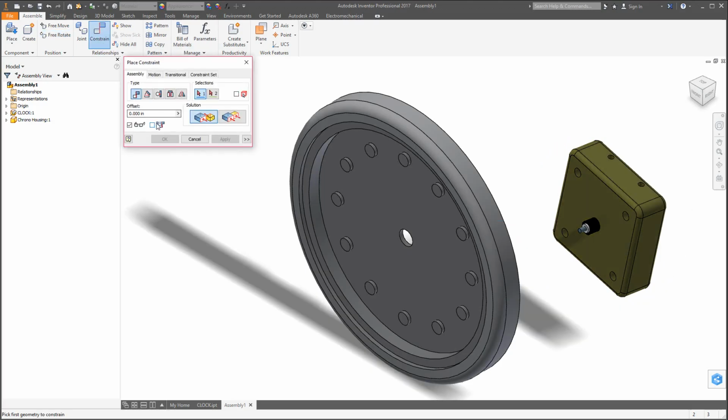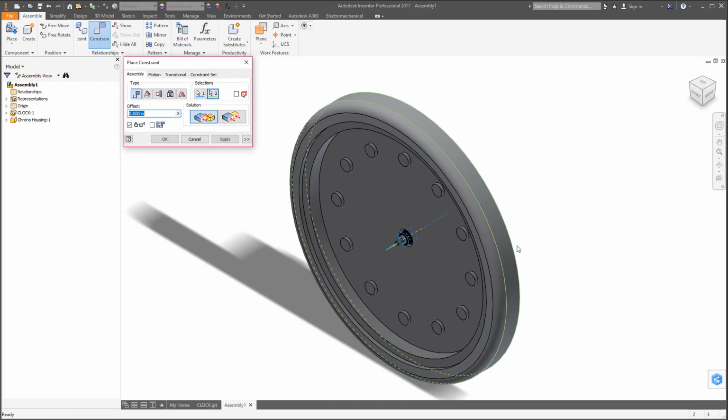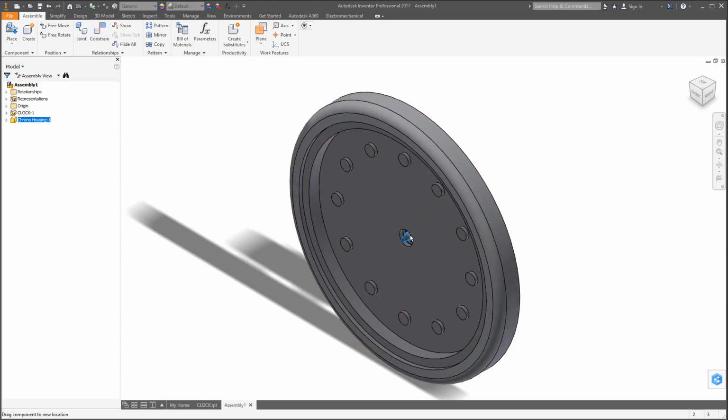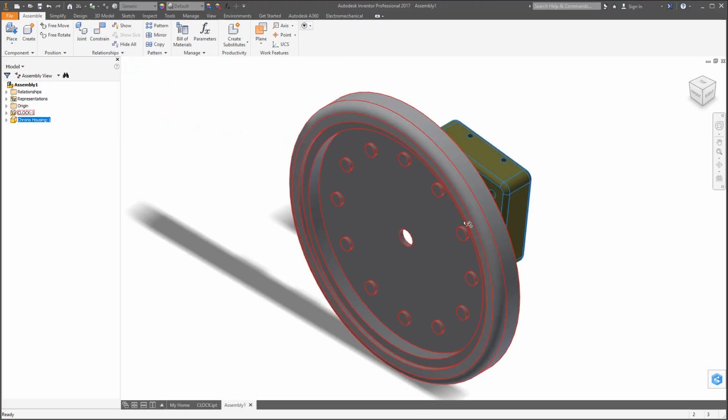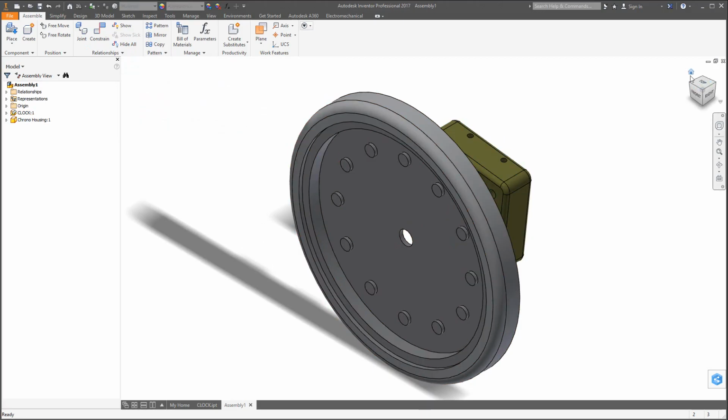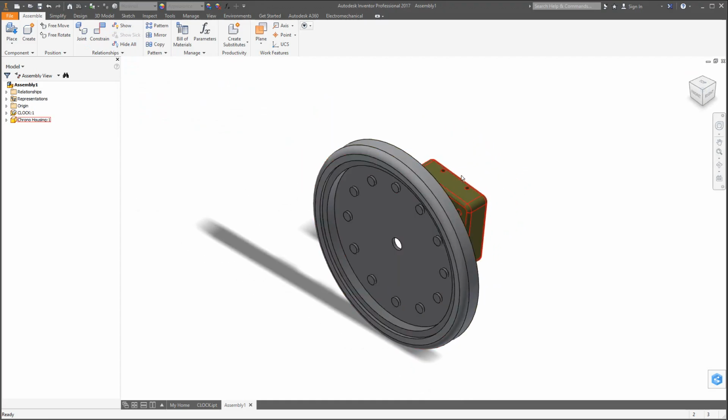But let's go to Constraint, and now I'm going to go ahead and constrain the center line axis on this black sleeve and hit Axis, and then I could just select the outside face or the inside face, any of those for the axis, and you'll see it position itself. Hit Apply, and I'm going to hit Cancel for a moment so I could grab this and carefully drag it out. Now notice you could easily flip it and rotate it the wrong direction. I'm in the home mode here, which is isometric. Make sure that those holes stick up